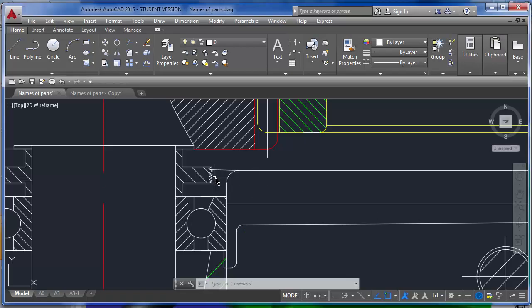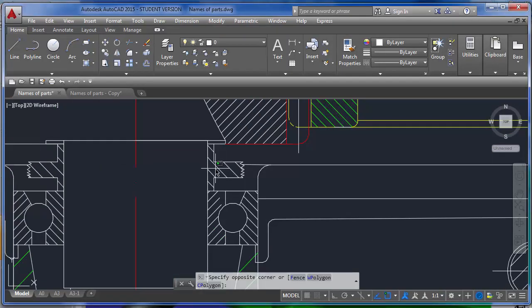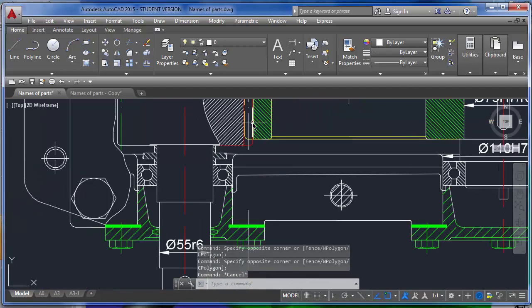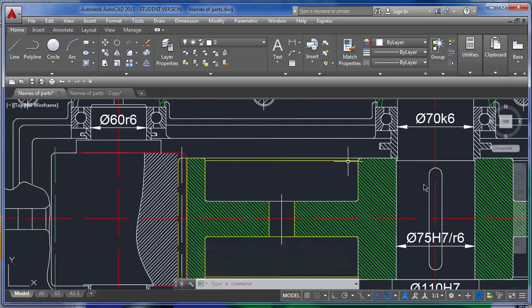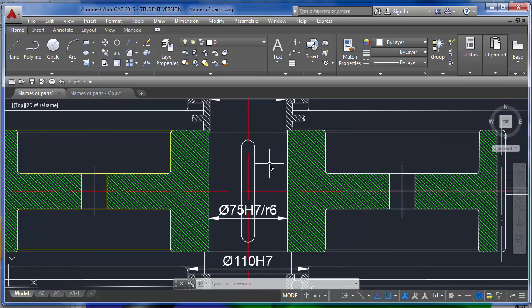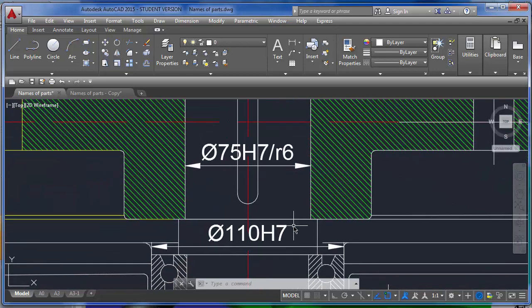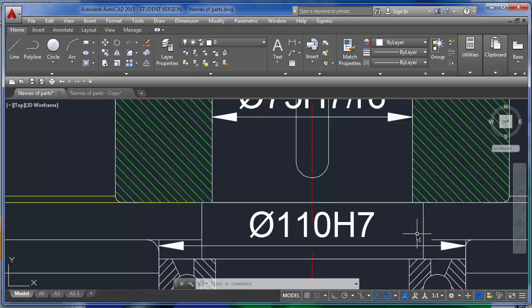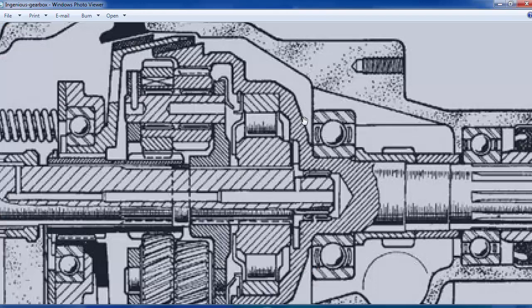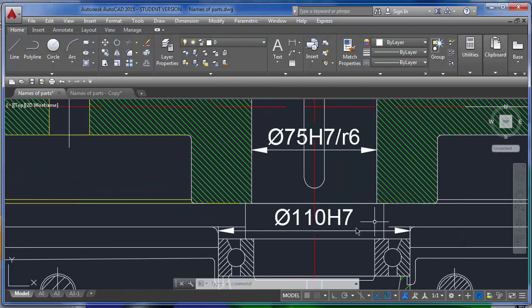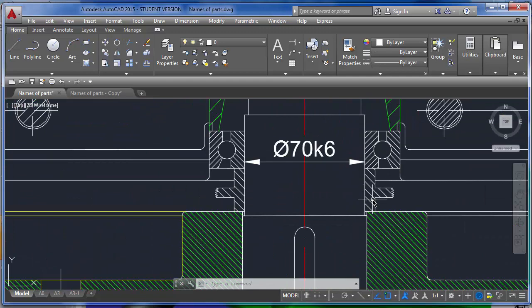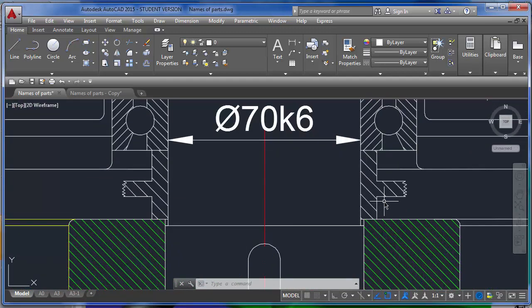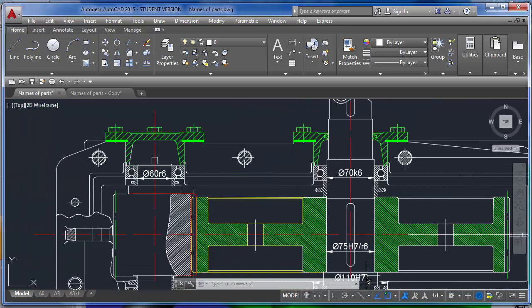So in our design we have this thing actually. It's a ring, and it's also here. In the output shaft, Laoshi was saying you don't need it on this side because this shaft has a sort of structure here, like I showed you in this gear. This structure is made out of the casing, and here it was made out of the shaft to support the gear and bearing. But here we have used it. It's okay. We have used it on one side, not on both sides.